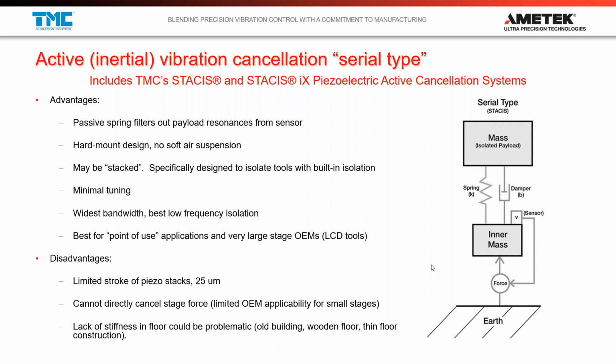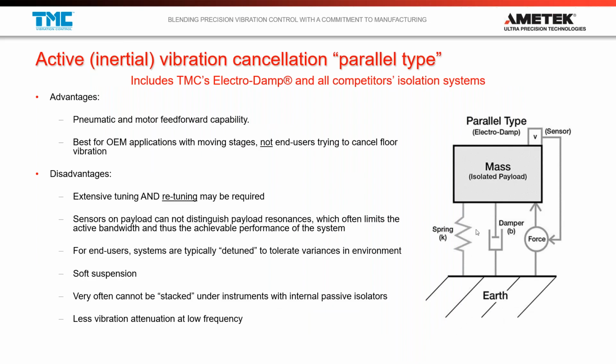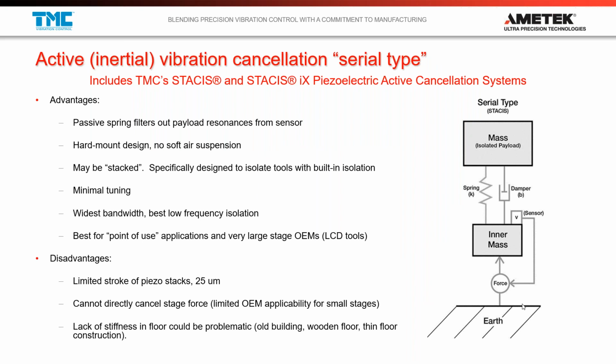So you have your piezoelectric actuator bearing the load of the inner mass, which then has a spring on top of it, which is bearing the load of the entire system. So you have a load bearing stiff actuator, which is different from a load bearing soft spring and non-load bearing actuator.